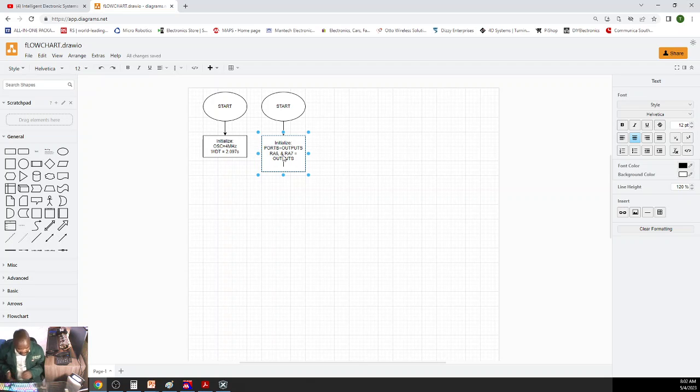The timing I can decide, but the timing has to be so small that the eye won't be able to catch it. If I switch between the 2 7 segments at 1 second, the eye will see that you are switching between them. Only one 7-segment is on at a time, and that won't really display a constant 2-digit number. To display a constant 2-digit number, I need to create a timer 0 interrupt of a very small timeout. Let's just say something between 100 microseconds to 1 millisecond. I can choose any of those two.